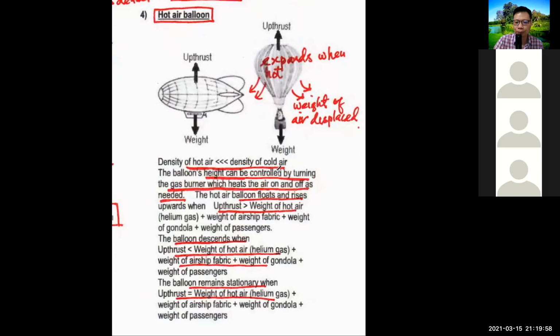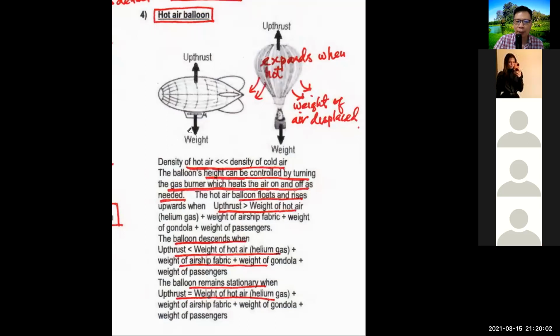Justin, are you here? Justin Yip? Yes, teacher. Justin, can you explain how a submarine sinks into the deep sea? There are ballast tanks. What to do with the ballast tank? The ballast tanks allow the water in. It's used to control the volume of water and the depth from the surface of the sea. Yes. If you want the submarine to sink, you need to open the ballast tanks and let the water flow in. The weight increases and becomes bigger than the thrust, so it will sink.